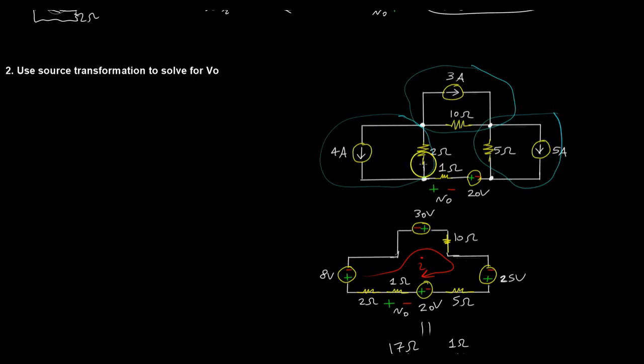Okay, so essentially what I've done is I've noted the direction of each current source and performed a simple source transformation. So if I look here, for the first case, I have 4 amps going into, I kind of just isolate them and think of these terminals by themselves. So A and B, for example. I have 2 ohms here. What is that equal to?